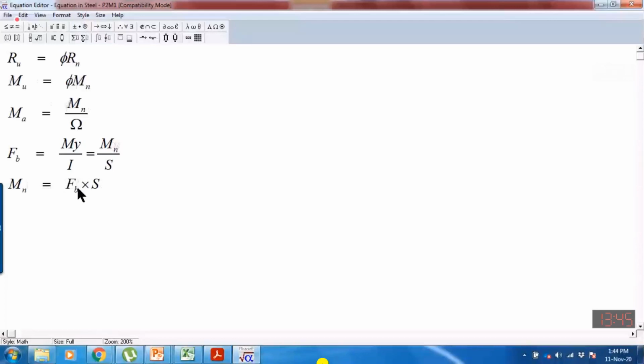Fb is the material strength, so we can also replace Fb with Fy. So bending strength can be assumed equal to the yield stress, and then this will be equal to the capacity. But this capacity is the elastic capacity. So if I am comparing, I will substitute the Mn value in this equation.